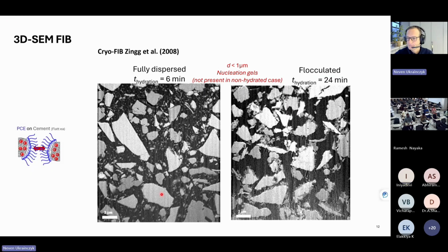And here we have the plasticizer inside, and why do they work? Because especially this second generation, they are called polycarboxylate, because we have the adsorption of the polymer on the cement surface, but not only of the main backbone chain. We also have these steric effects, because then we have even better dispersion of the cement particles.